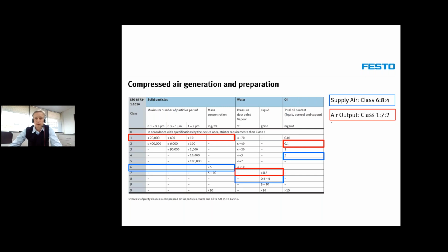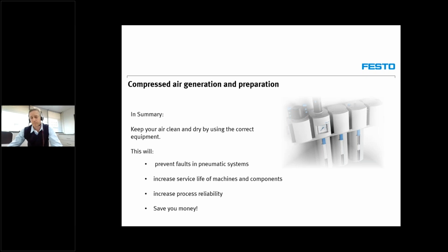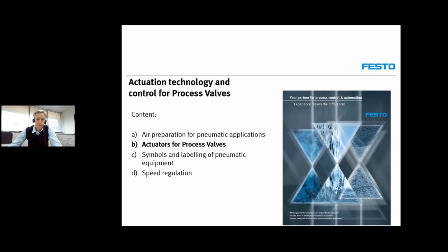Now, what have we learned about proper air preparation? Keep your air clean and dry by using the correct equipment. This will prevent faults in pneumatic systems, increase the service life of machines and components, increase process reliability, and in the end, save you a lot of money.